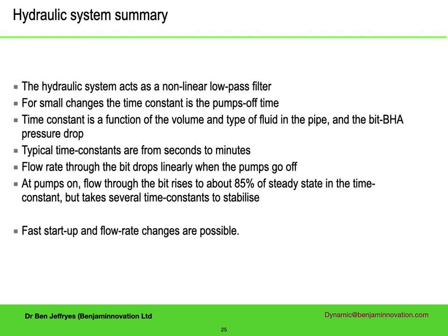So to summarize, the hydraulic system looks like a nonlinear, low-pass filter. For small changes, it is nearly linear, and the time constant is the pumps-off time. This is a function of both the volume and type of fluid, and the pressure drop at the bit and along the pipe. The time constant is from seconds to minutes.